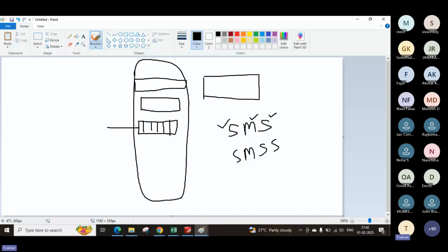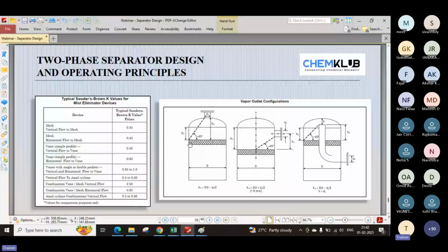The first one is generally for the inlet devices. The middle one is for the helping media like a vane pack or mesh pad. The last is cyclone separators or anything else you have. So generally, to reduce the height of the vessel, not the diameter, you use multiple devices in your separators, and that is how you can help reduce the height of a vessel.